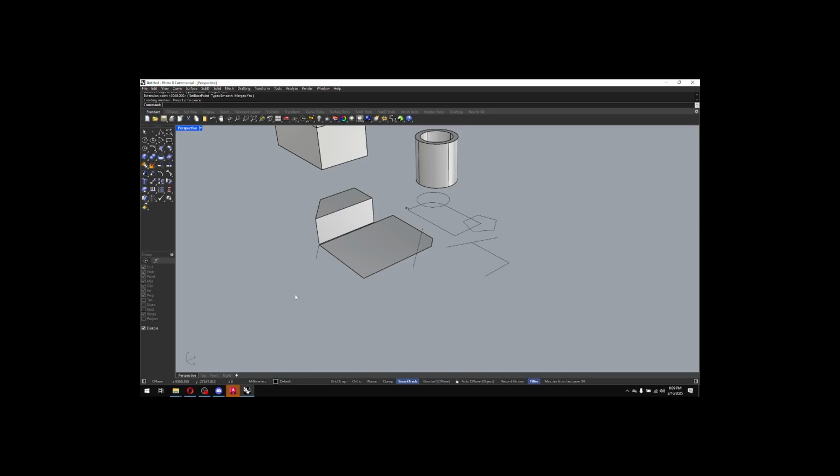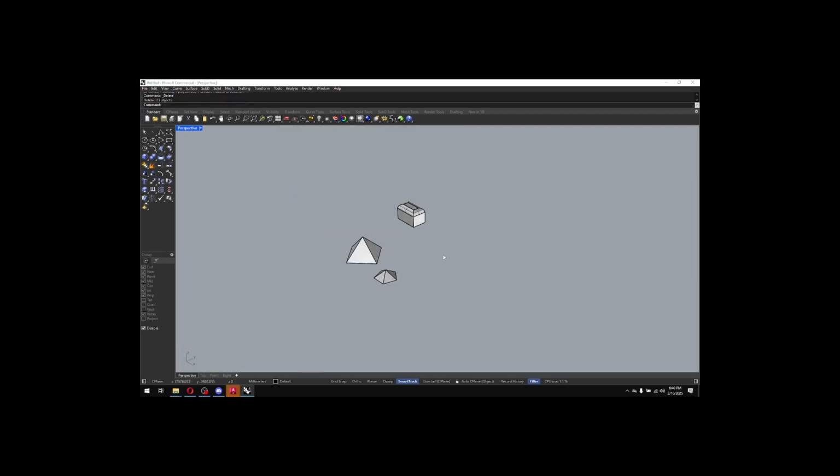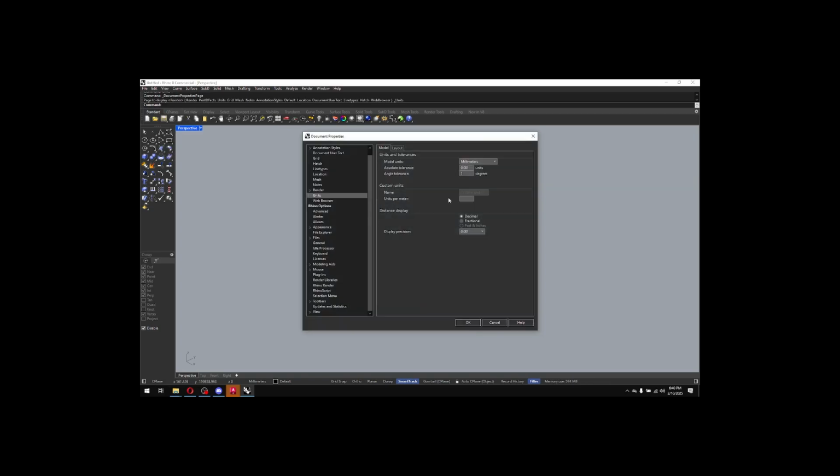Extrude, that's a big one. So this is where we haven't even brought in our CAD file yet. Let's bring in our CAD file. First, I'm going to change my units. Should have done this first. I draft everything in inches. That's pretty standard for most offices. In AutoCAD as well. Feet is usually what you'll get from surveyors, civil engineers, things like that.